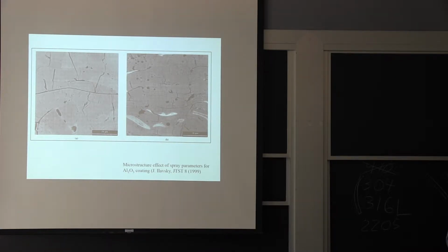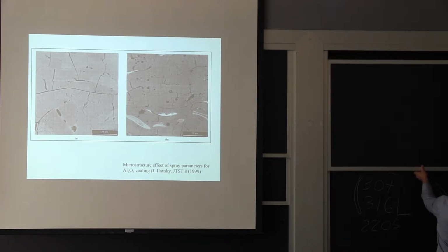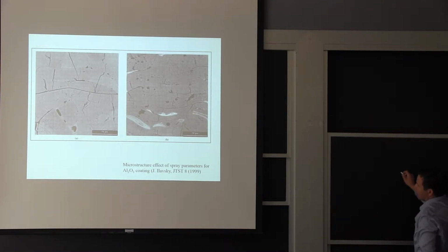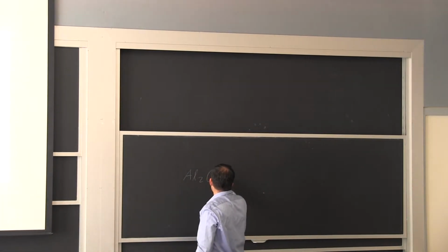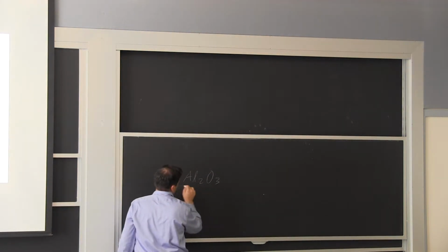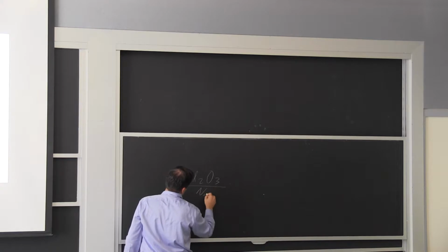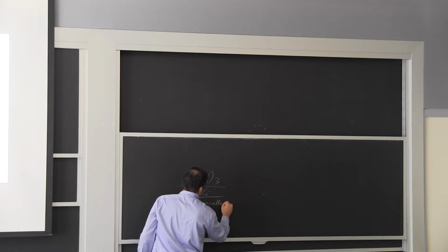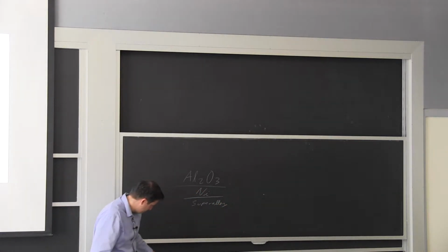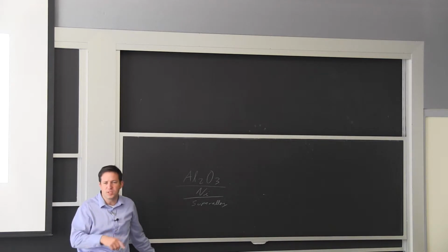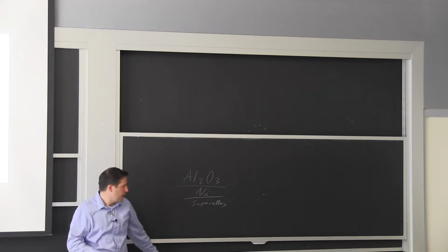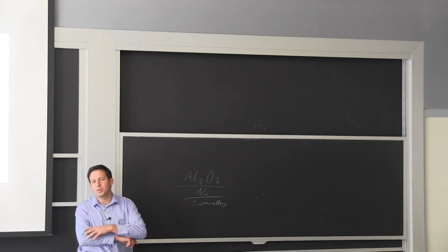It's unfortunate because essentially everything that resists higher temperature expands less, and that's what is exposed to the highest temperature here. We have sometimes the opposite. So we talk about essentially the ceramic here. They have alumina, but zirconia is more common for this application. But anyway, if I have the alumina and I have the nickel layer, and then say I have a superalloy. And when we say superalloy, a lot of times it just means a little bit like the aluminum. You have a lot of precipitate, you have a lot of second phases in your base structure. So it's almost a metal matrix composite.